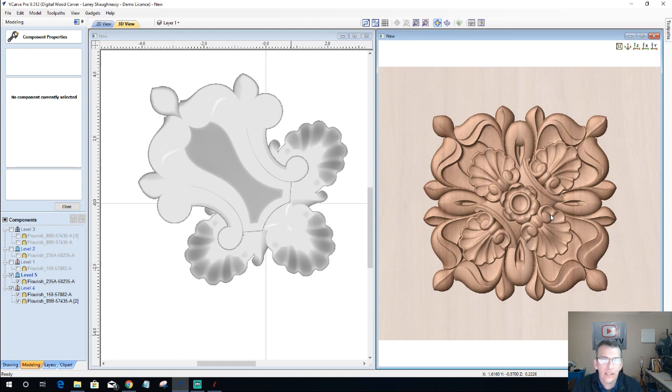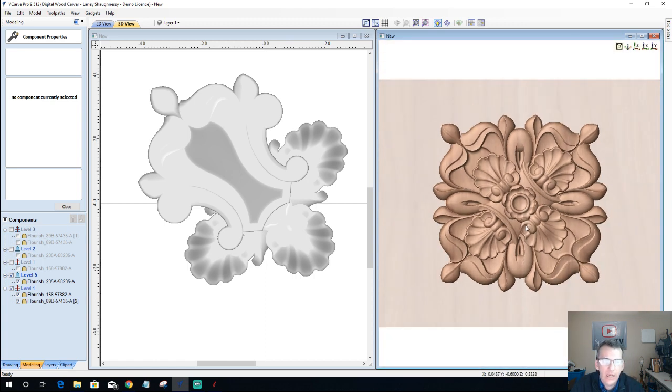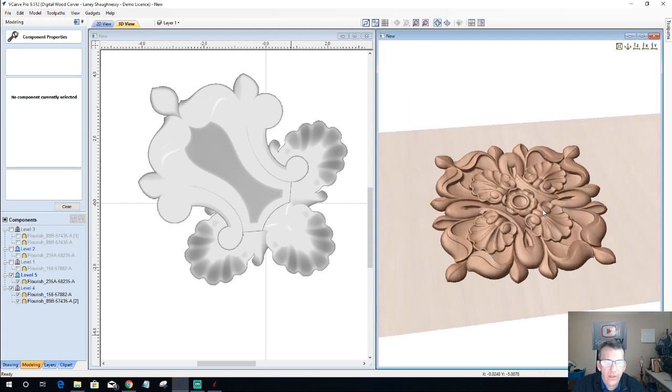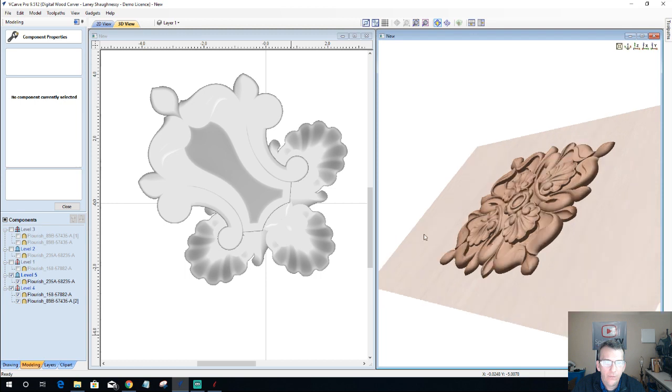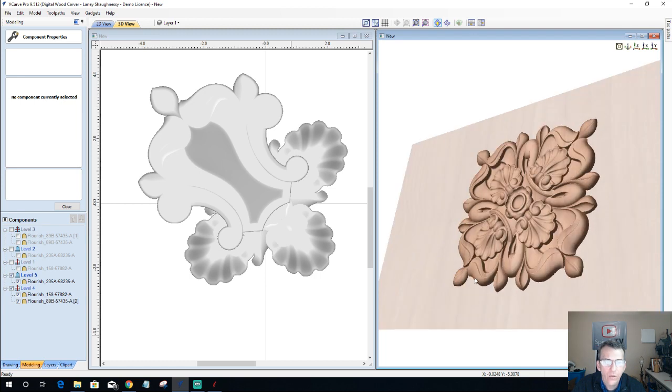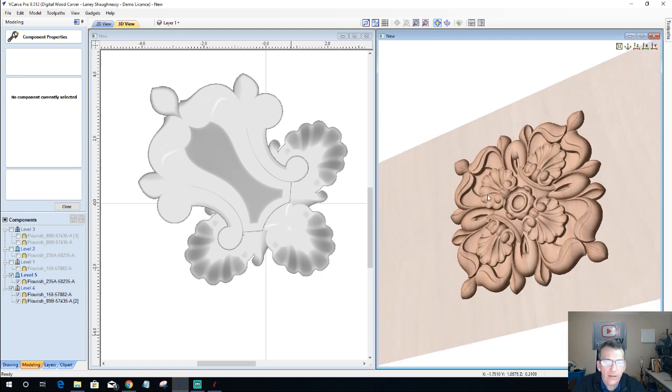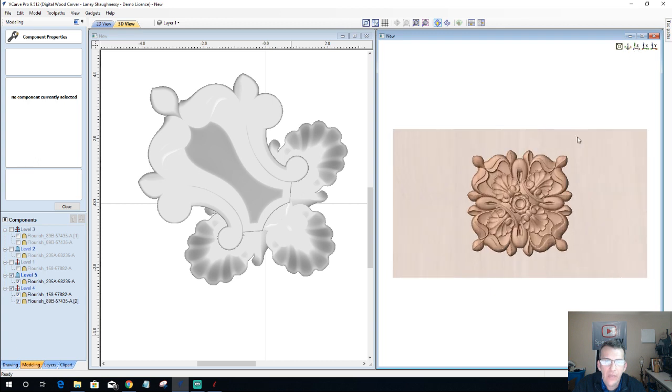It could be a ceiling medallion, where this gets cut out for my ceiling fan motor and all that stuff. So far, we've got this little medallion-looking thing blended together. If we do a little bit of a tilt and a rotate, we can get an all-around view of it. I think I'm good. I don't want to give myself any more base height. I think 0.15 will be a nice looking base height to combine that together.